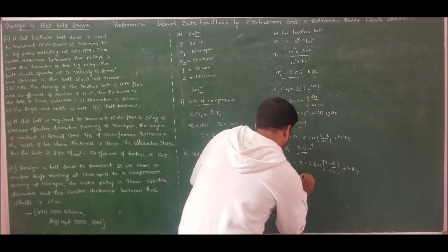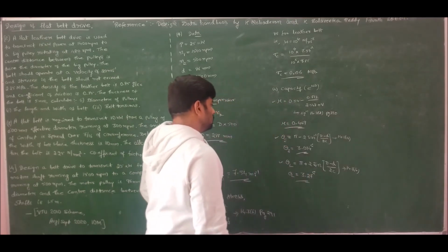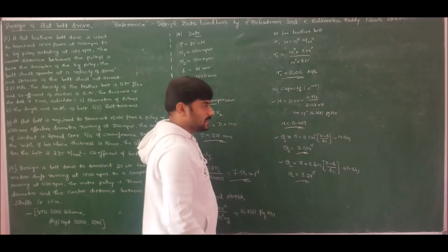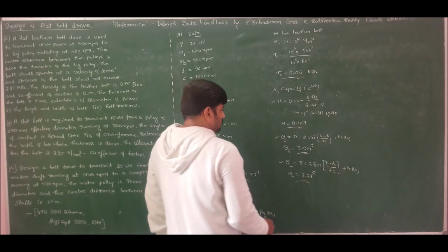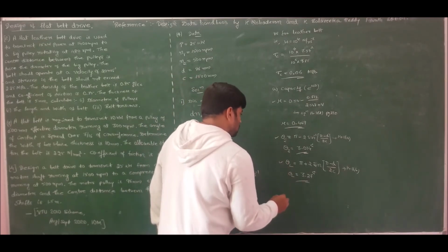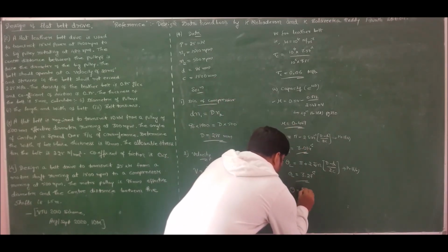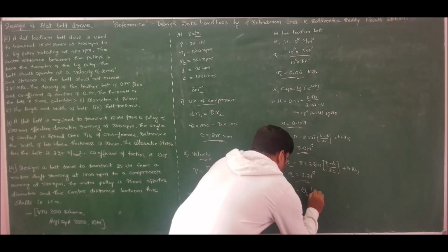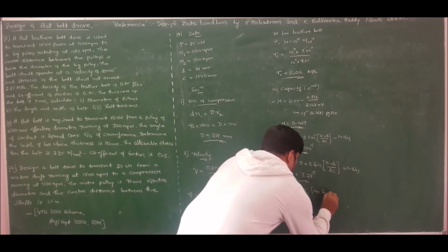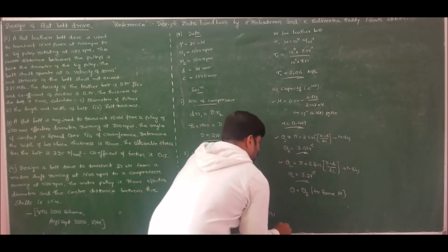So the angle of contact for the larger pulley is 3.27 radians. The superscript c stands for radians. Now I can find the capacity, where theta is nothing but theta of the smaller pulley. Theta is equal to theta s for the same, or constant, coefficient of friction.